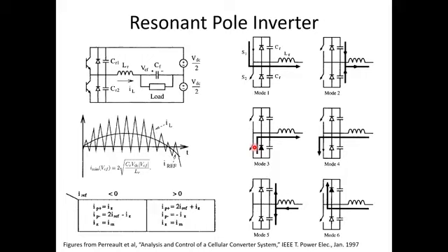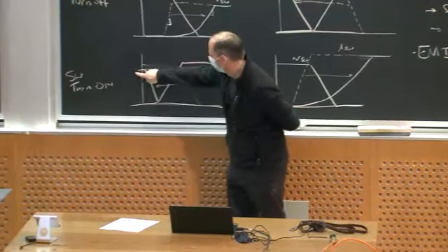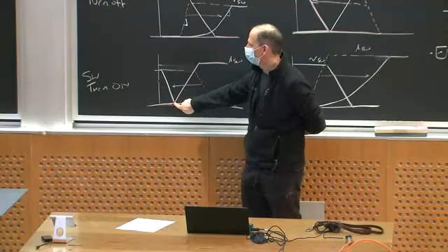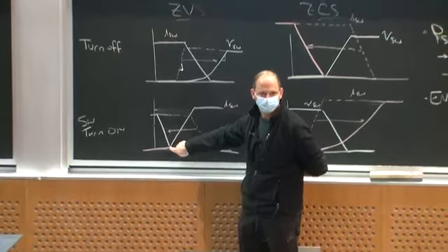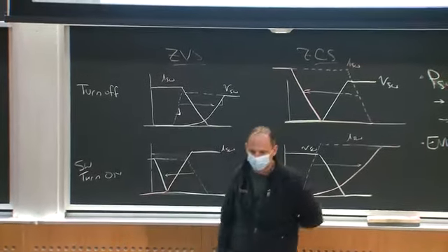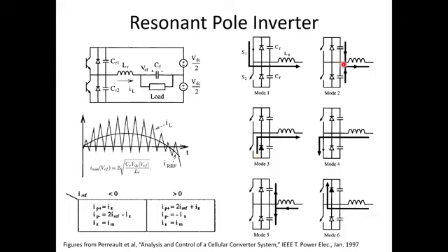0, right? So in fact, by turning off the top device and having this inductor ring with these capacitors and turn the bottom diode on, I am essentially, boom, creating a case where the bottom switch voltage is 0. That means at any point after this node voltage rings down from VDC to 0, I can turn on this switch, okay?